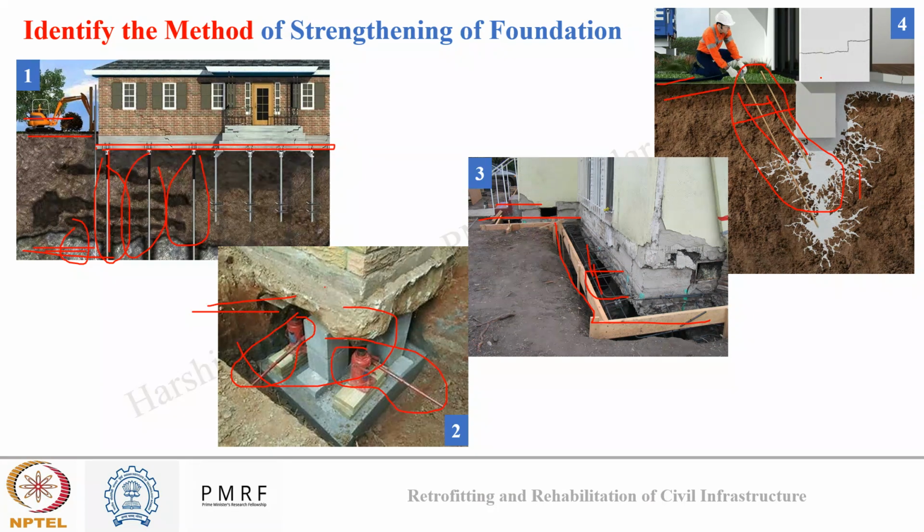So from inside also, between columns, if I have space, I can get some area from which I can access the existing footing, and if I can provide section enlargement there, I can try. Okay, sir. If there is a large space between footings, then from inside also I can access those areas, no? Yes, sir.